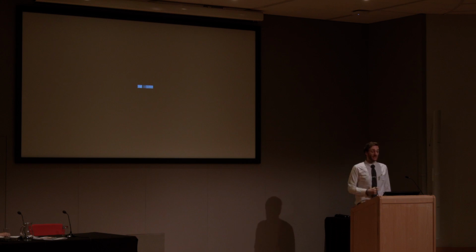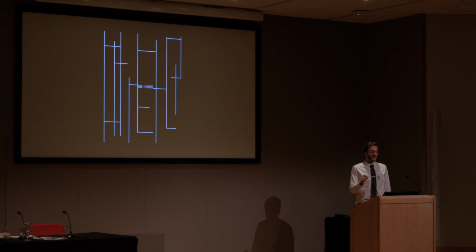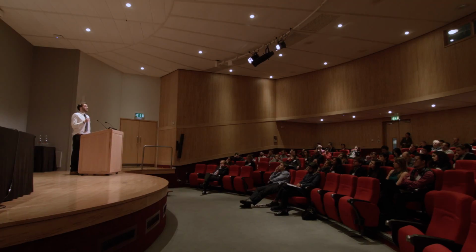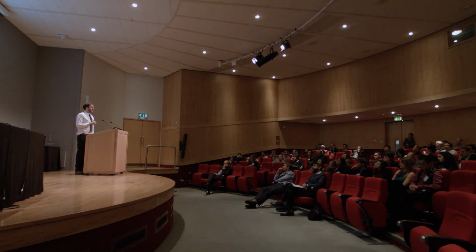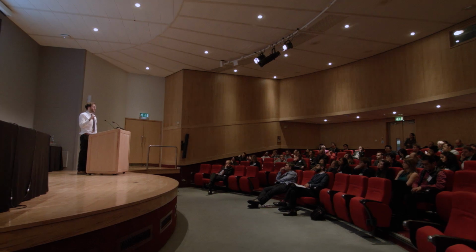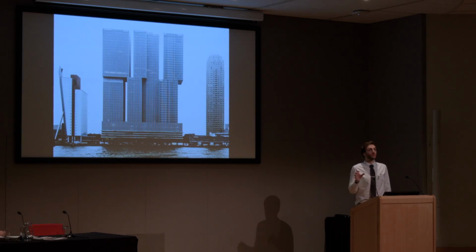Next, what we do is couple in our 1D network model. So we start to explicitly model the total building system now. Each one of these lines might represent a lift shaft with a lift going up and down, or a ventilation shaft, or a stairway, a stair pressurization system. Then when we make our assessment and we define our fire safety design and expand it back out to the building, at least we've explicitly considered the total building system, so we can have more confidence about how we predicted the fire is going to spread, grow, and how smoke is going to affect the rest of the building remote from the fire origin.